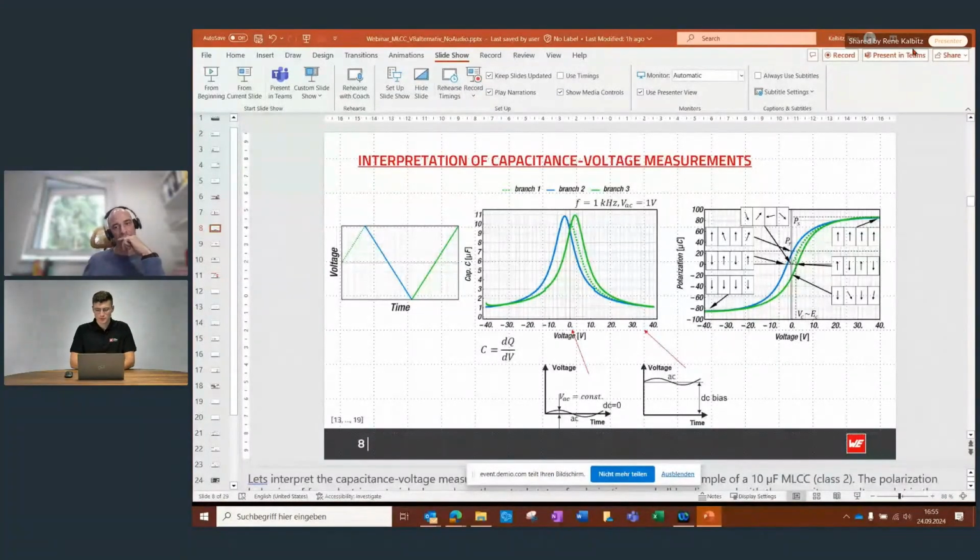What can one do about the capacitance dependence of MLCCs during the design-in? Well, all you can do is oversize. That's the basic strategy. That's what you do. You oversize the capacitance. That's what you always do. There's nothing else you can do.